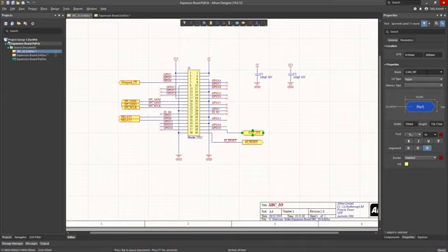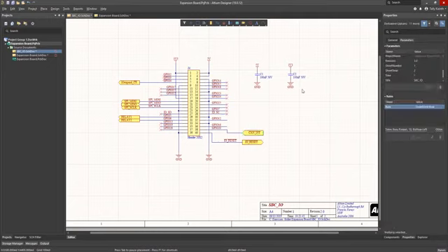This brings us to an important point regarding connections on a schematic and between schematic sheets in a project. Net labels only connect on the sheet that they are on and do not provide connections between schematic sheets, whereas ports provide the interconnections between different schematic sheets in a project. This is a very important concept and one that we will revisit.